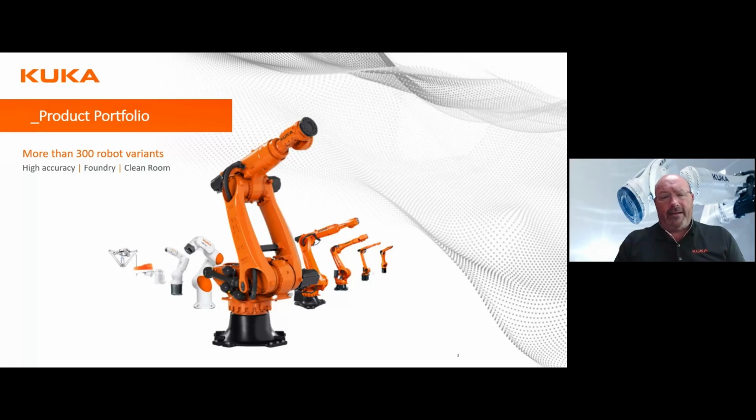And then other things to consider and to be aware of is the robot accuracy and repeatability. A simplified way to think of these, they're kind of interrelated topics, is to think of accuracy as a measurement of how closely a robot moves to the desired position in 3D space. Whereas repeatability is the ability of the robot to consistently reach the same position time after time. Most industrial and collaborative robots have accuracy and repeatability ratings measured in fractions of a millimeter.